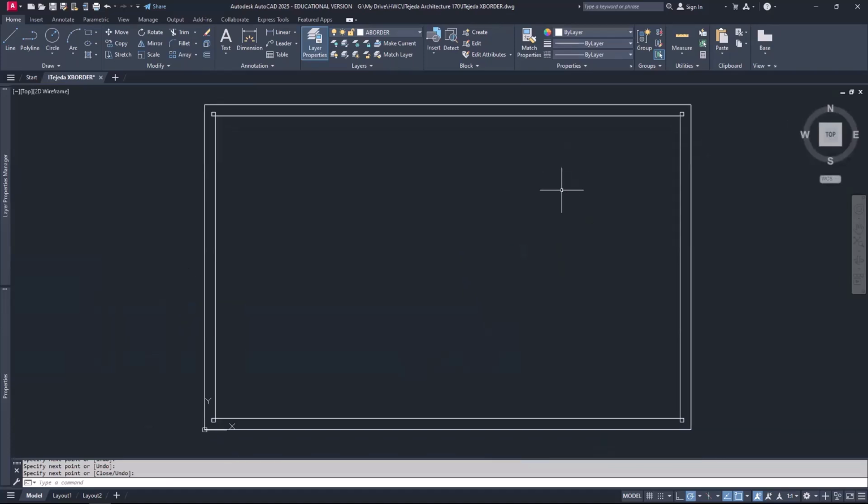So now I do want to get a global thickness. So I have to convert this back to a polyline. And the way to do that, I simply just join these line segments. So I'm going to type J, enter. And I'm just going to window all of it like this. And then enter. It tells me 12 objects converted to one polyline. That's what the command line says.